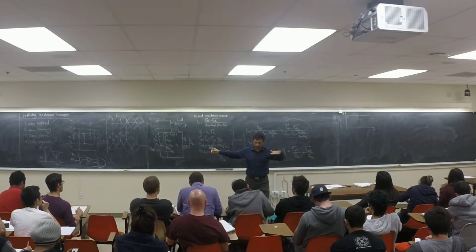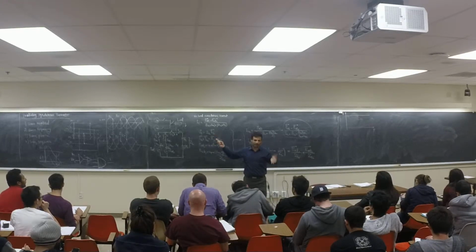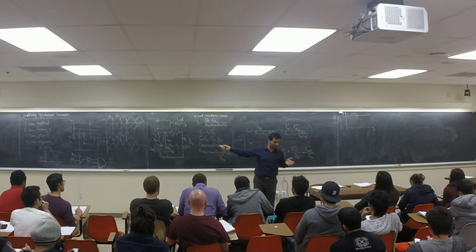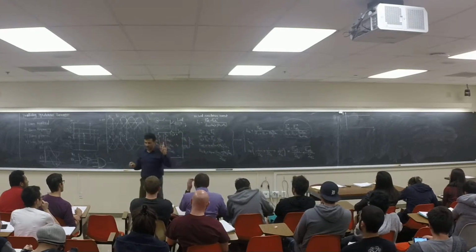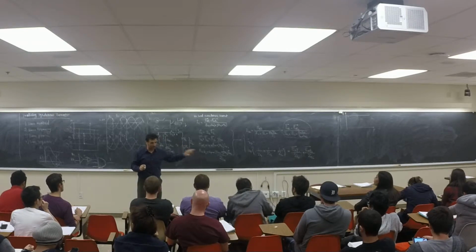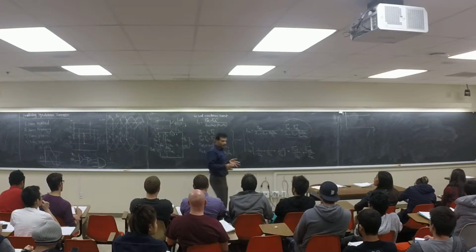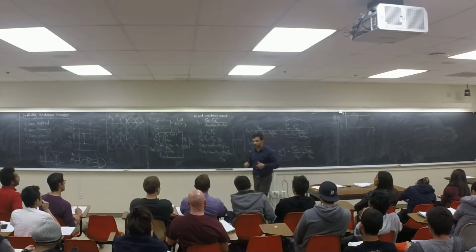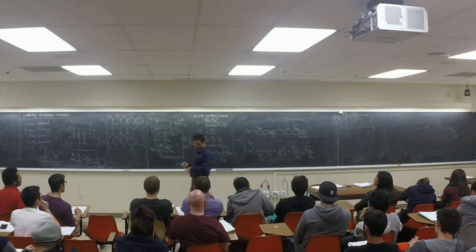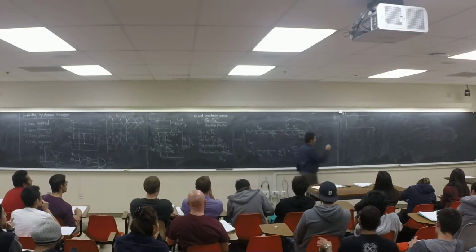Now the frequency is 50 hertz. I don't know, it's whatever you calculate. It's going to be, for example, 3000 RPM, right? You need to go calculate that. My point is, the machine is still synchronous, right? You can say how much the speed of the machine is based on the frequency. But you know, there is no perfect generator, no perfect machine. When you increase the load, the speed is going to drop, right? So when the speed drops, what's going to happen?